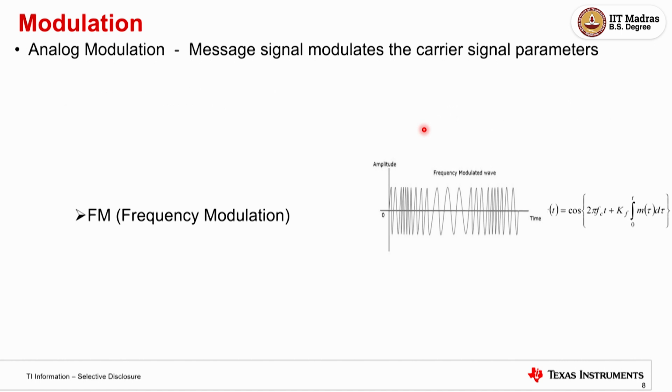There is something called frequency modulation, which is FM. So what does this do? Same thing, you had the carrier signal, but I didn't change the amplitude. Amplitude is remaining the same, but I'm actually changing the frequency. Whenever my message signal is moving, I'm increasing or decreasing the frequency of my carrier around it. So the carrier frequency is 2 gigahertz, but it will drift by whatever your message signal frequency is.